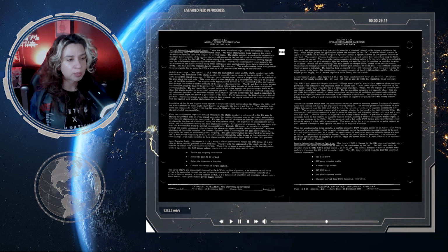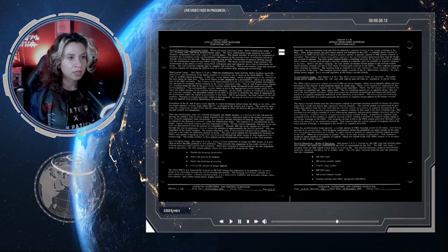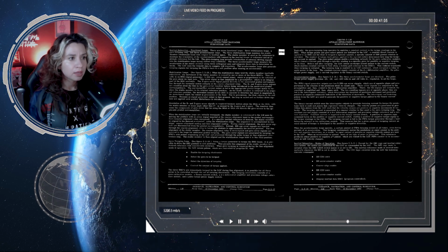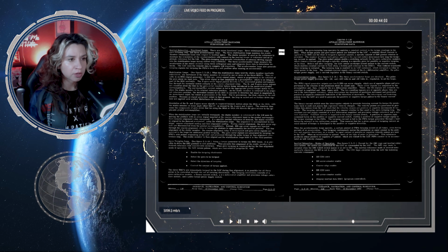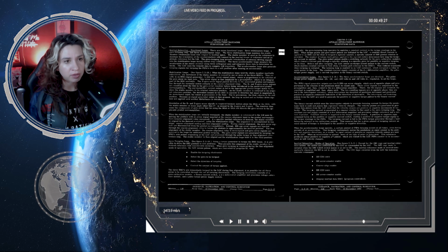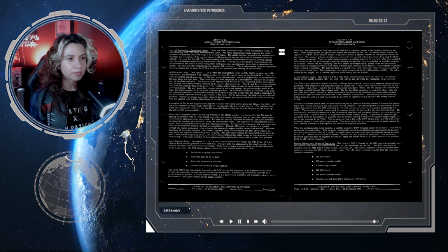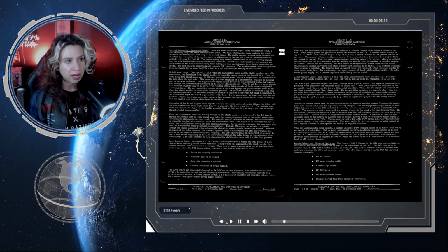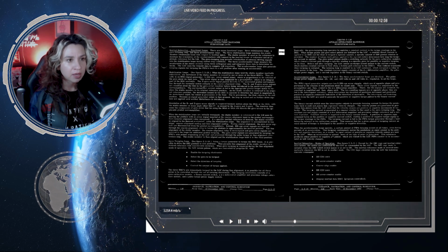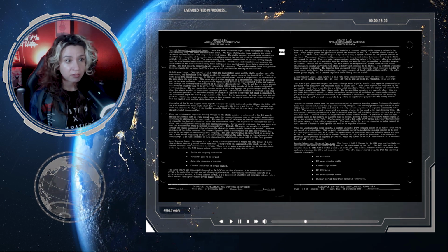The pulse torque power supply provides positive 20, negative 20, and positive 120 volts DC, and a positive 28 volts DC regulated to all the loops. The PIPA signal generator outputs are two 3200 CPS error signals, which are of opposite phase and proportional to the rotation of the pendulum about its output axis. These error signals are amplified by the preamplifier and then routed to the AC differential amplifier. There, the 2 signals are summed, the resultant is amplified, and then phase split.